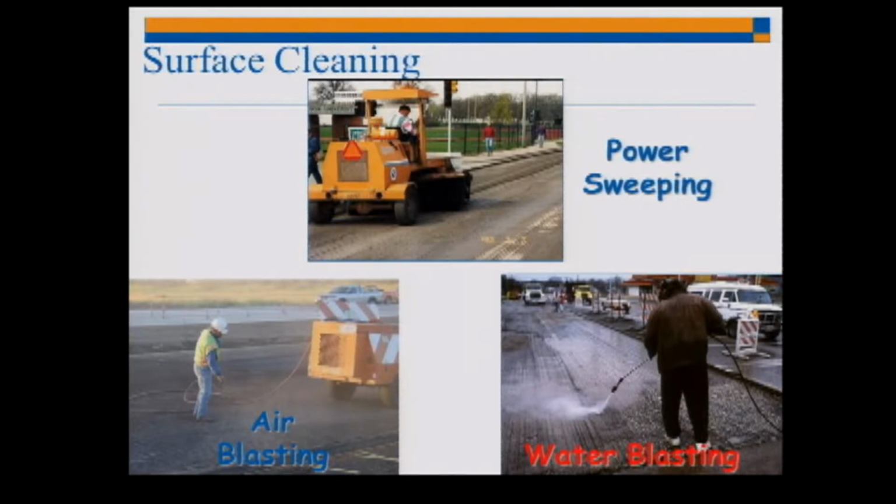Again, it's important to clean the surface because the bond is the most important part in your assumption of your design. So you can wash it or sweep it, but you just need to get the oil and the dust and debris off the surface.